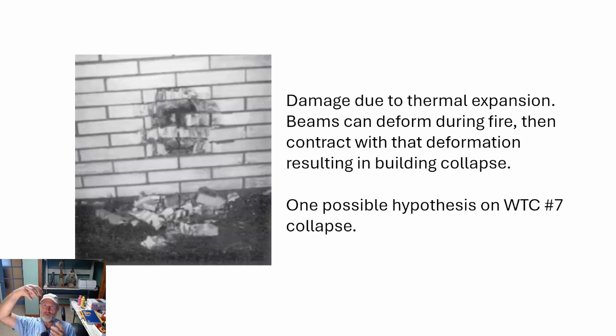So I'm going to use more of a mechanical engineering term, and that's an eccentric loading on a column. So if I had a column, and I put the force on top of that column right in the center, it really is crazy how strong that is. But if I take the exact same column and I put the force just off on the edge, it'll buckle much easier. I mean, the numbers are staggering how much easier it is to buckle that.